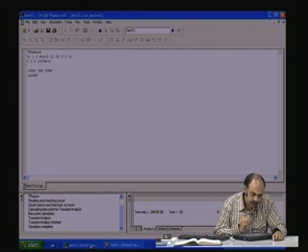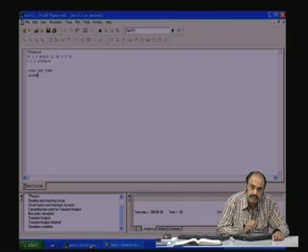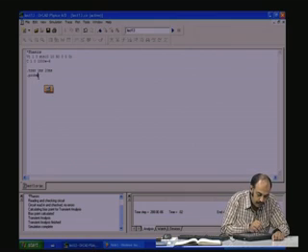So, going to this PSpice editor, we have here Vi as the input between node 1 and 0, a sine wave source, 0 DC offset, 10 volts amplitude, 50 hertz, 0 rise time, 0 fall time, and no phase shift.